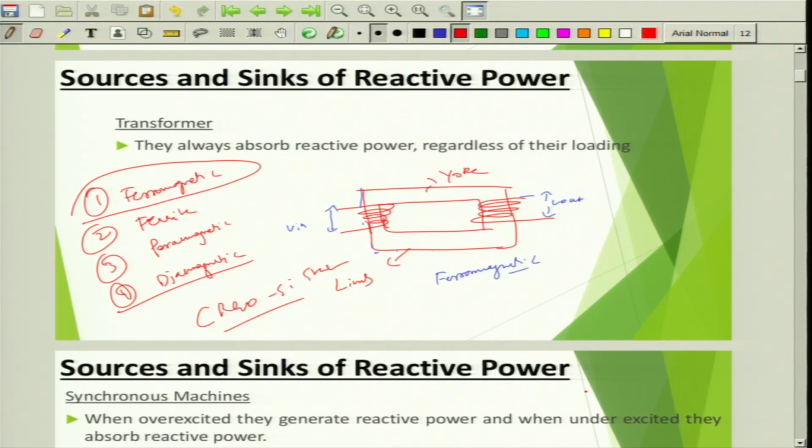So typically what happens, if you connect the primary, you need to excite the transformer. We call it charging of a transformer. When you connect to the primary source, it would draw some current. Let's say there is no load connected. As you see here, there is no load I am connecting at the secondary side. So in the primary side you are connecting this transformer to some voltage source. It could be LV or HV, that's immaterial for us.